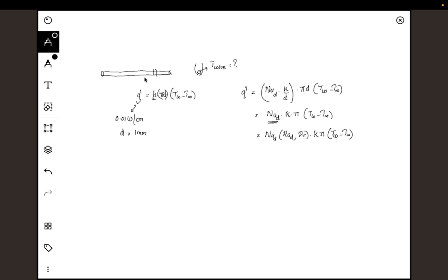Previous week when we were solving a problem where heat flux is given and you are asked to find the surface temperature. Because you do not know the surface temperature, the problem that we ended up is this will depend on say alpha, nu, beta. All these are dependent on them. All these values are functions of T film, which is itself a function of TW plus T infinity by 2. And we do not know this TW. So that was a problem. So you cannot solve this problem in one go. So there is an iteration that is involved.